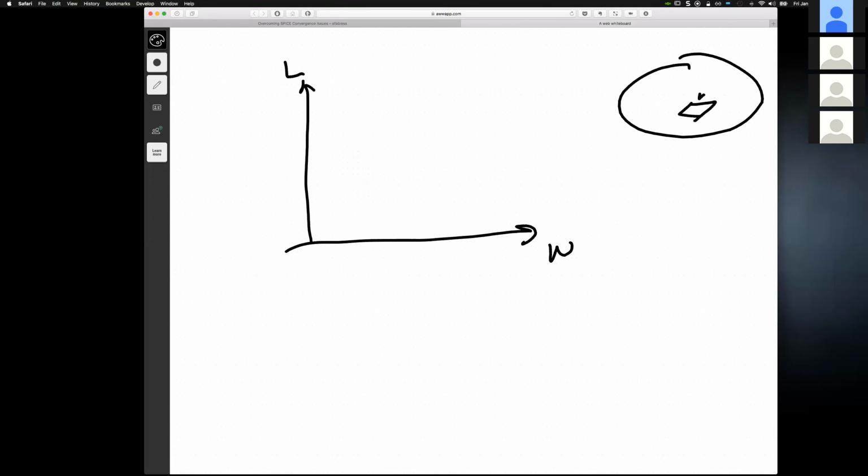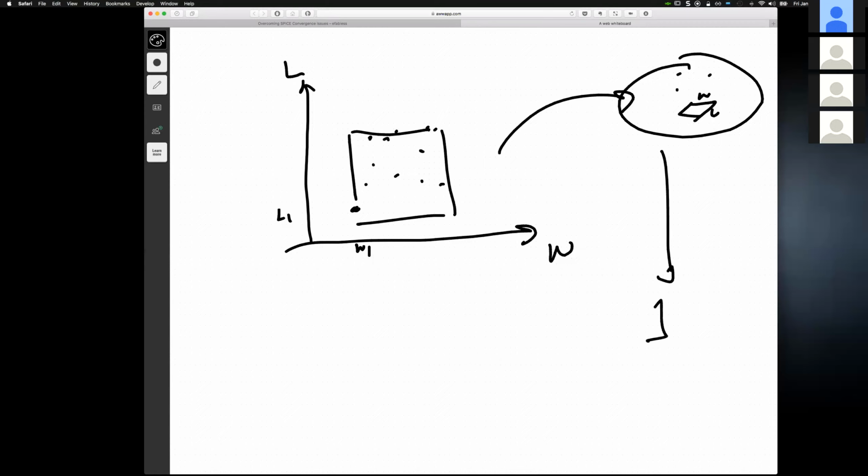They will have W's and L's in arrays, and then you will end up with points on this chart. They will say, here's W1, L1, okay? They choose certain areas, and say, I'm going to manufacture these on a wafer, measure it, and create the transistor model. Fit it to that.